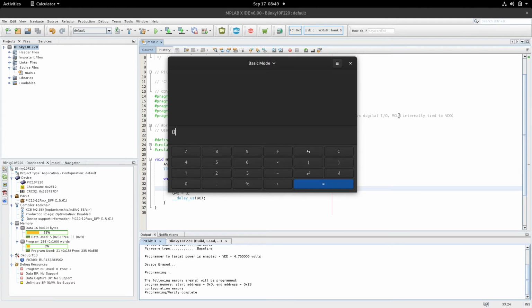So let's go over the same calculation, this time with a prescaler. We said that our instruction cycles are 0.5 microseconds. It takes 256 instruction cycles for the timer to overflow. If we apply a prescaler, let's say 64, then we are looking at about 8 milliseconds. If we divide 1 million microseconds by 8,192 microseconds, we will find our frequency, which puts us at something like 122 Hertz. And that frequency is high enough to drive an LED.